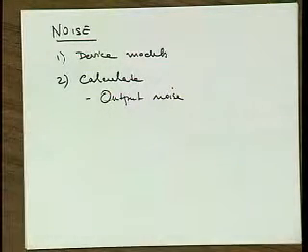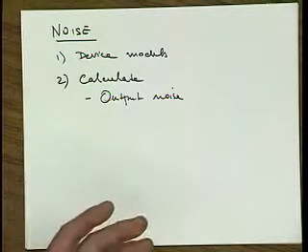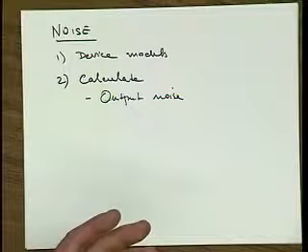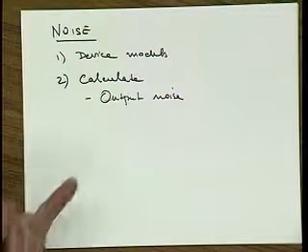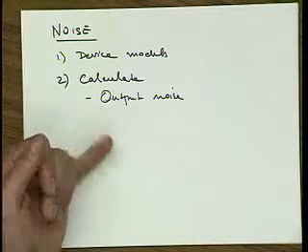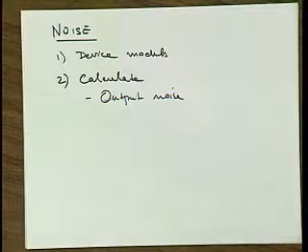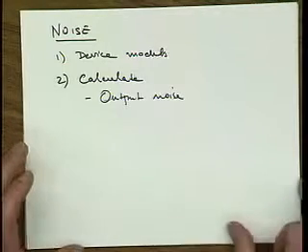So if we have a circuit with lots of elements in it, transistors and the like, then of course they're all going to have noise sources. There may be dozens or hundreds of those. What really matters in the end is how much of this noise makes it to the output of the circuit, right? And these calculations are fairly tedious, but they're kind of straightforward, right? We almost have a computer program to do it, and sometimes we have to play computer and just use that program.